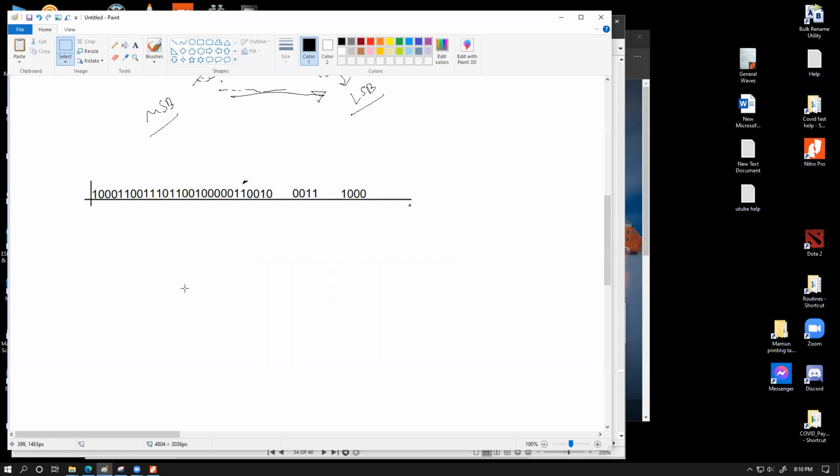The parallel to serial converter basically merges all of the individual parallel data into one single stream of data, and this shape of the data is what we call serial data. This serial data is then fed into the communication channel. So if it's a wire-based system, it goes out as high voltages and low voltages. If it is an optical fiber system, it goes out as bright or dark. For how much duration do you have dark, for a step size of 125 microseconds, and then for how long it was illuminated? That's what we measure.